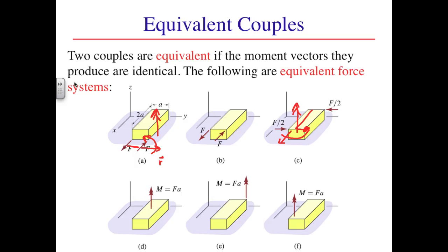It should be mentioned that this claim of identical influence rests on the assumption that we can treat the body as rigid and not deformable. A force produces local deformation about the point of application. If we were able to see the deformation accompanying application of the load, we would see local deformation features about the bottom corners of figure A that would shift to the top corners in figure B. We would similarly see other local deformations at points of application of load in the other figures.